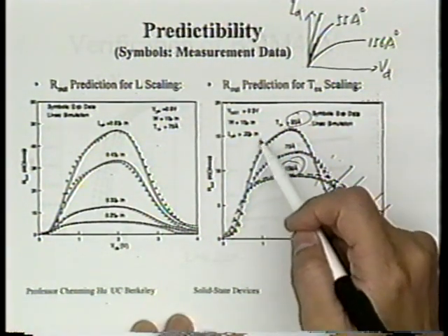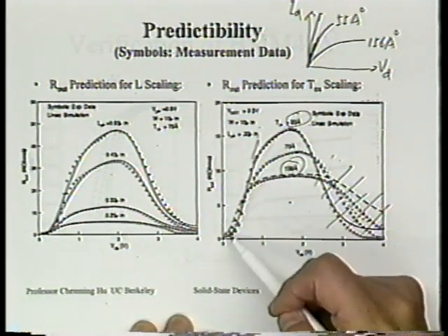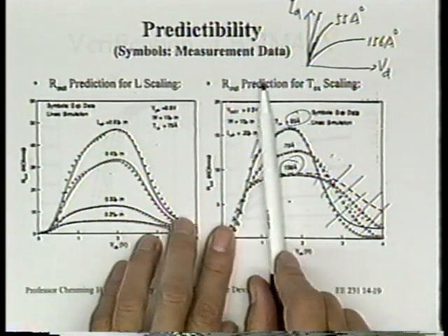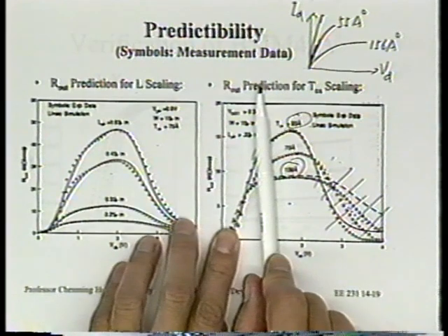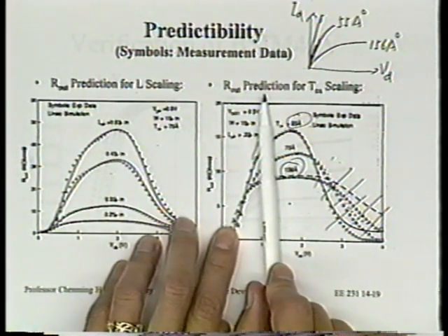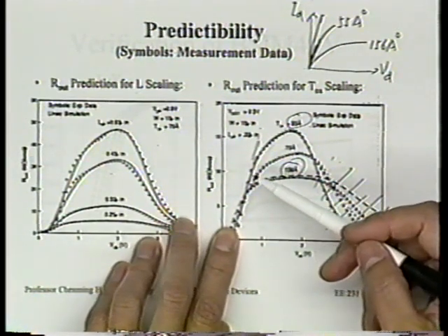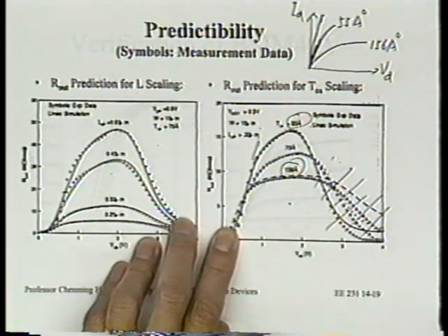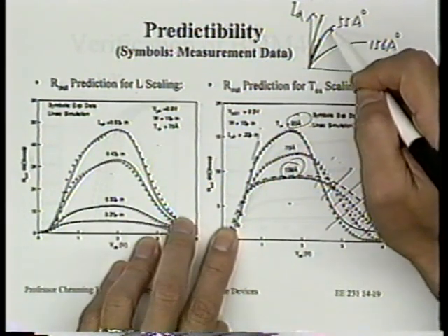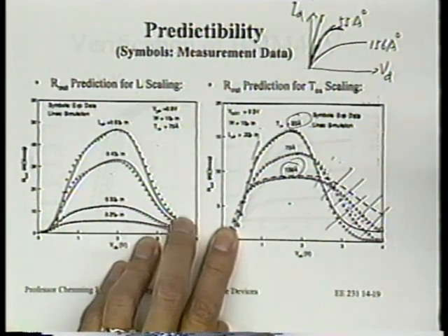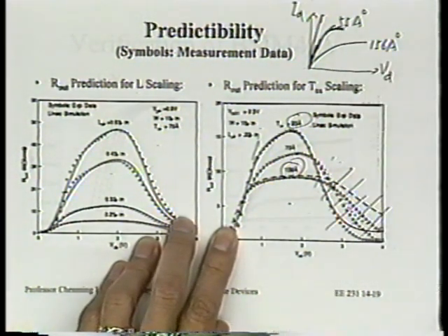Right? Remember the slope having to do with channel length modulation. Remember that? It's a linear function of VD, right? You do notice there's a regime where it's fairly linear, right? It's pretty good. Do you agree? Is that right? Okay. And the larger slope means what? Meaning the R out is rising faster, meaning it's getting saturated faster. Is that right? That means there's less channel length modulation. When this curve becomes very flat, it means no channel length modulation.